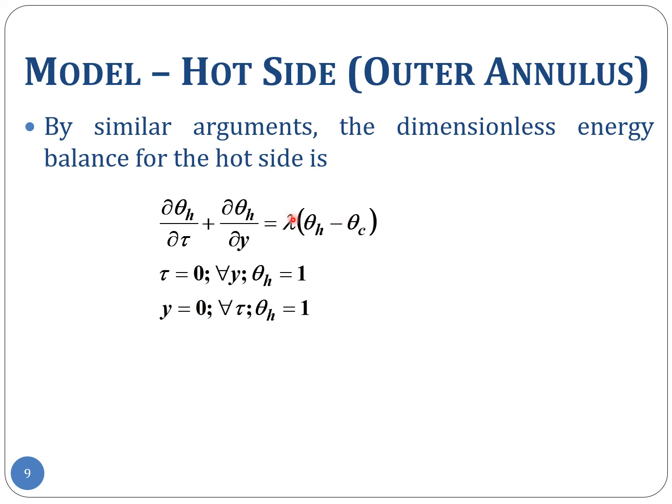So looking at this equation, this lambda, which is UAL by M C_P V. The numerator U A L gives a measurement of the rate of heat transfer from the hot to cold fluid, and the denominator is a measure of M C_P V, and that is the convection. So which dominates?